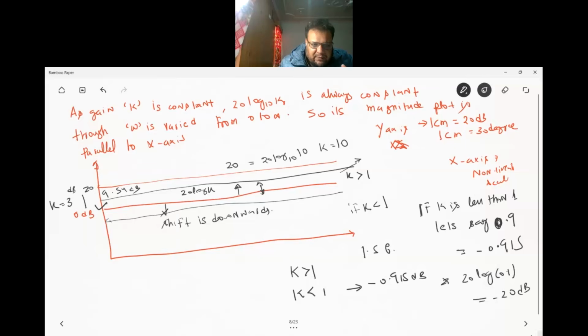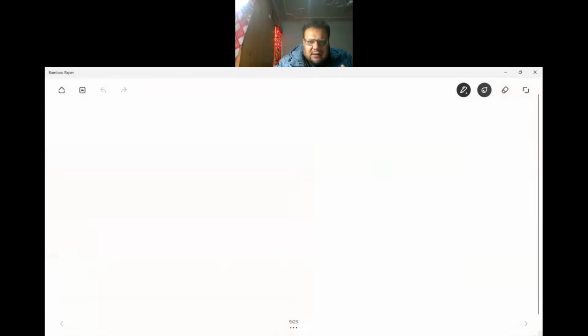This is the meaning. Whenever you are making a Bode plot, your x-axis is the logarithmic axis, which the semi-log sheet takes care of itself. Whereas on the y-axis, you need to get the magnitude in dBs, so whatever the magnitude, you have to multiply it by 20 log to the base 10. As far as the angle is concerned, it would be the same 30 degrees like this.